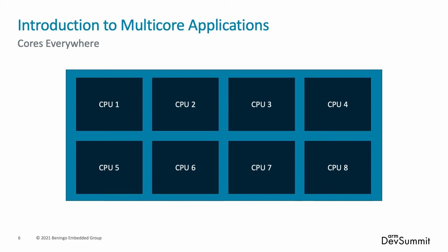And you start to see multiple cores being used in order to get all the work done. But it's not just that. Some of the advantages of multiple cores is that, yes, I can break up my problem domains or my execution environments, but they can also be used for protecting our device and creating isolation barriers within our applications, basically getting hardware isolation in order to help improve the security of our systems.